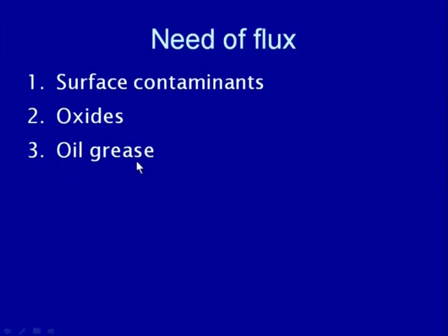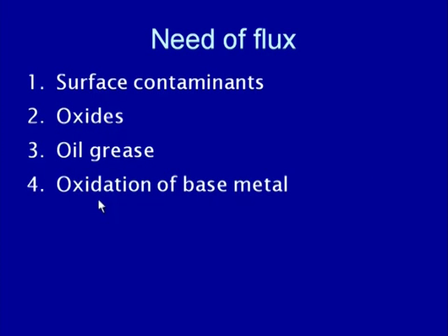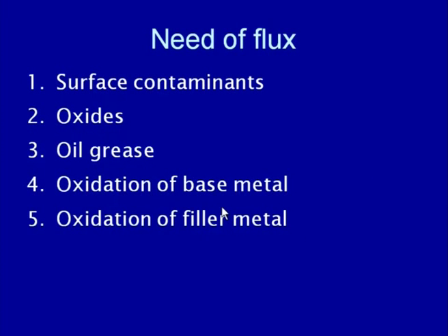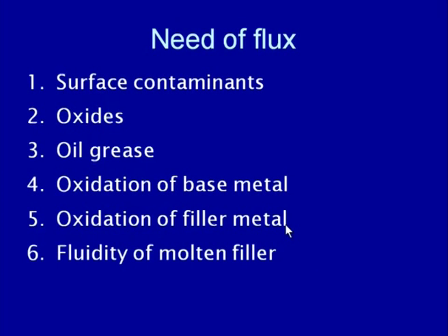The fluxes also help in removing the oil and grease present on the surface, and they prevent oxidation of the base metal and further prevent oxidation of the filler material also. So, there are various purposes for which fluxes are used in brazing and soldering: they remove impurities present at the surface, remove oxides, remove grease and oil, prevent oxidation of the base metal, prevent oxidation of the filler material on heating, and help in improving the fluidity of the molten metal, so that it can distribute uniformly between the fixed surfaces.